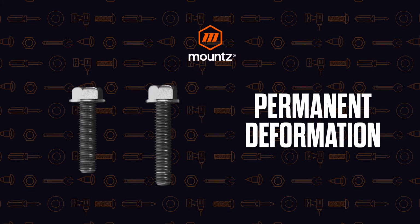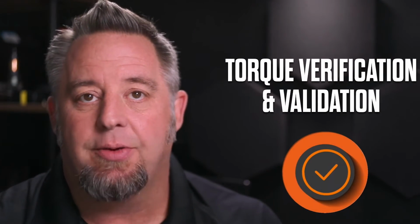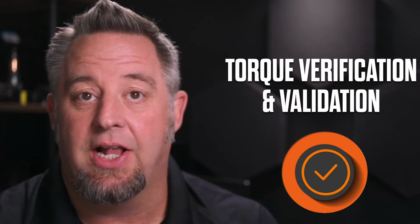And so that is how we can do testing to make sure that our torque values that we're calling for are what we need. Because the goal here is the clamp force and making sure that we have the right tension, and the torque is the means to be able to achieve that tension within the fastener. So let's take a look at the type of testing we can do during the assembly process to help ensure that we are getting the right torque values. And that can be done through the torque verification or torque validation process.